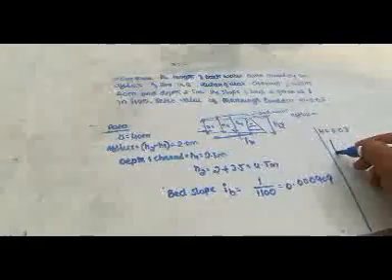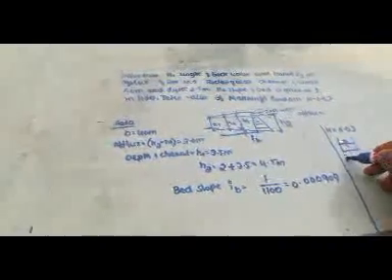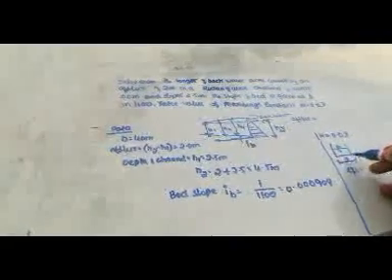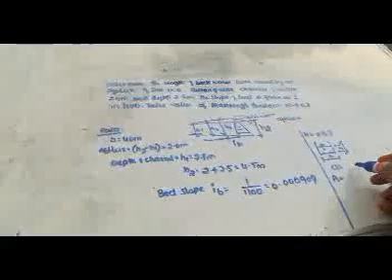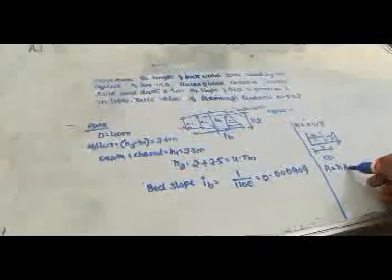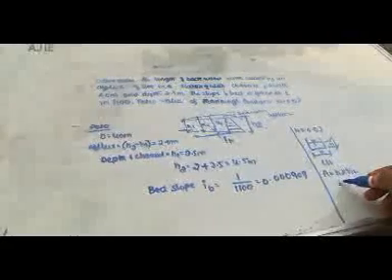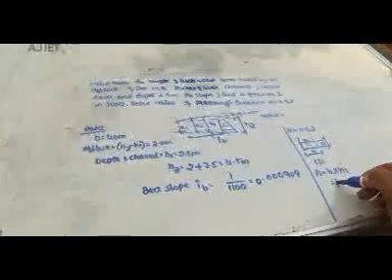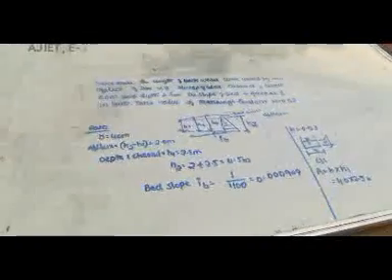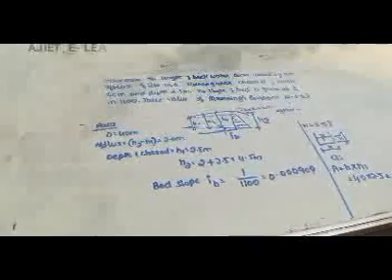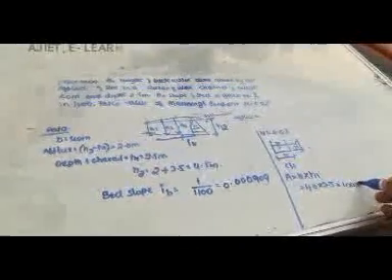And we know the area of the flow section. We can consider this a rectangular channel. If we consider the cross section, we will find the b and h values. So the area of the flow section A1 is equal to B into H1. B value is 40 and H1 value is 2.5. The rectangular channel width is 40 meter and depth 2.5 meter, as given in the question. So the answer is 100 meter square. Area is equal to 100 meter square.